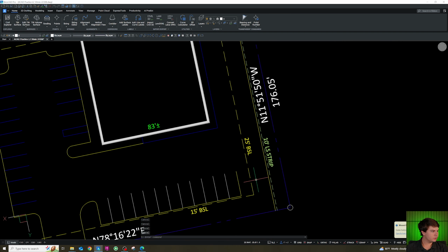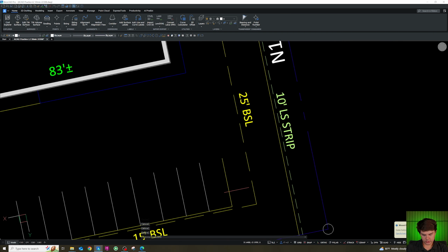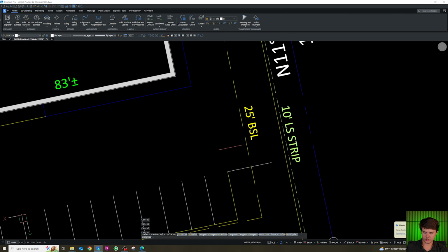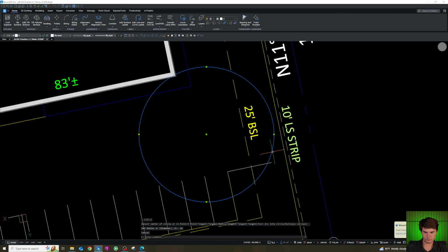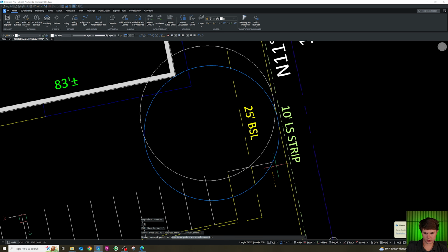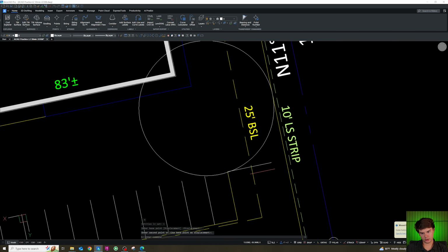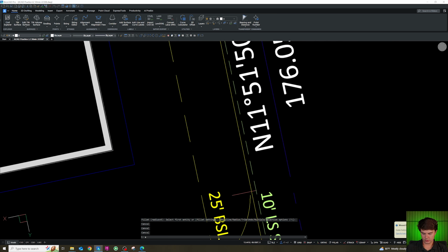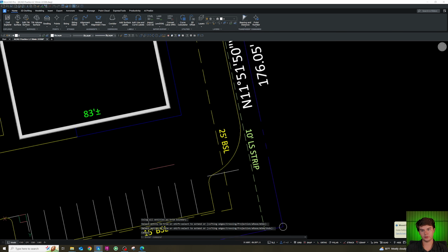Now it looks like we have a 26-foot radius here. Which it does not like, so I'm going to draw a circle, 26 feet. I'm going to move it and snap to the quadrant, to the nearest point on this line, and now I can move this orthogonally until it looks about good. Now I can fillet this here and extend this to the line, trim away here. Now you've got a nice curve for a car to drive on through.